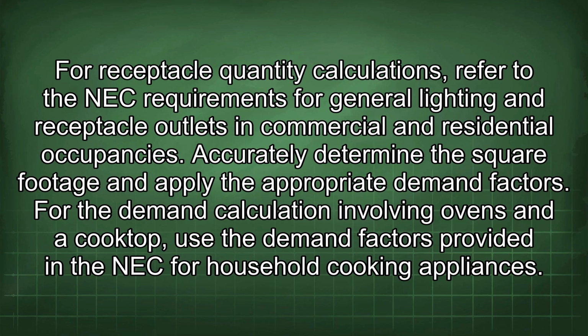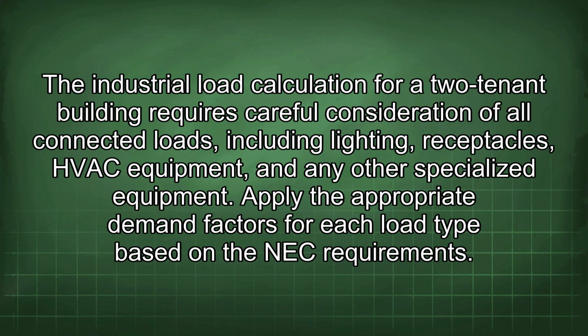For the demand calculation involving ovens and a cooktop, use the demand factors provided in the NEC for household cooking appliances. The industrial load calculation for a 2-tenant building requires careful consideration of all connected loads, including lighting, receptacles, HVAC equipment, and any other specialized equipment. Apply the appropriate demand factors for each load type based on the NEC requirements.